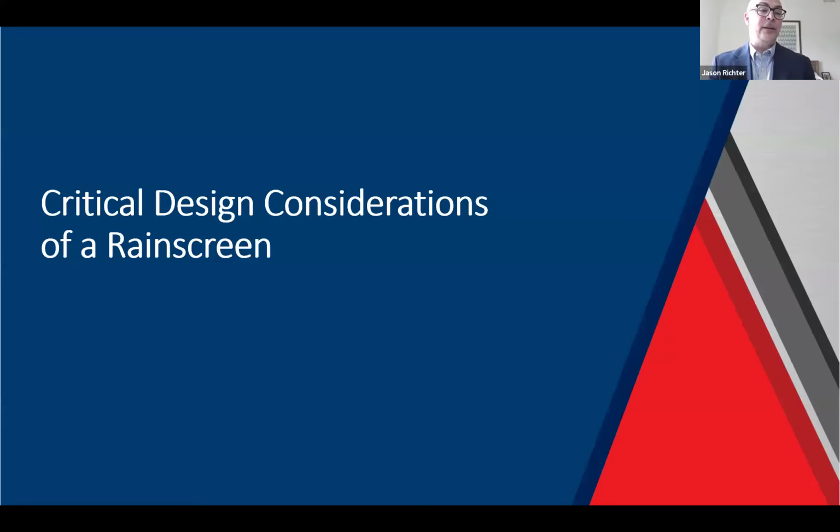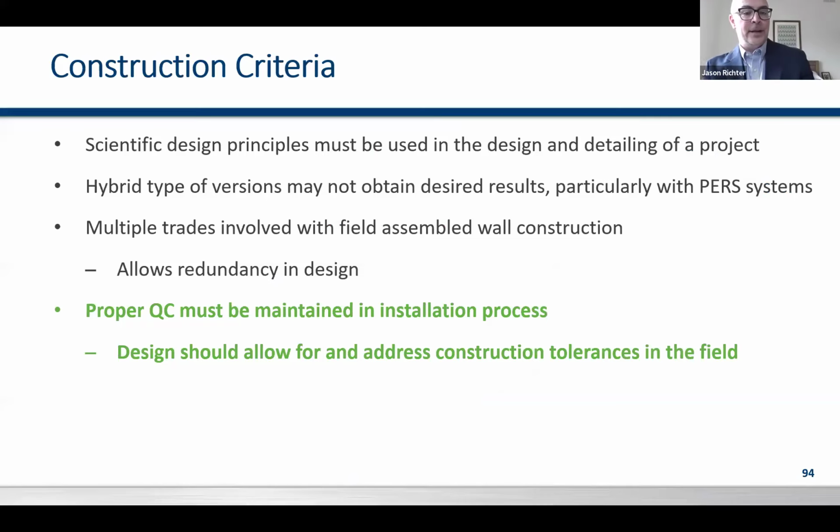Usually you're getting at least a 50-degree delta from exterior to intake temperature with that design. So on a 30-degree day, you're pulling in 80-degree air, which is a big advantage and helps reduce wear and tear on your HVAC.